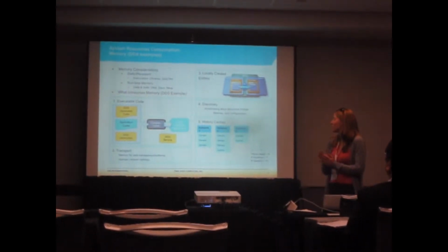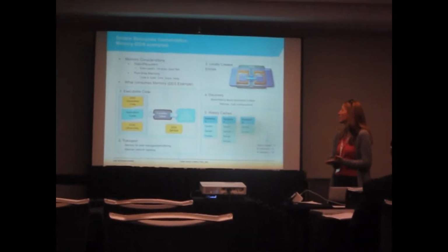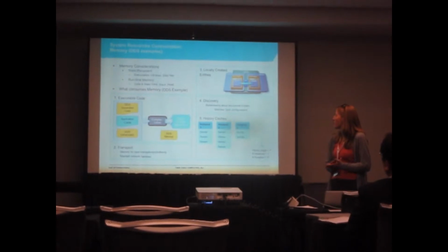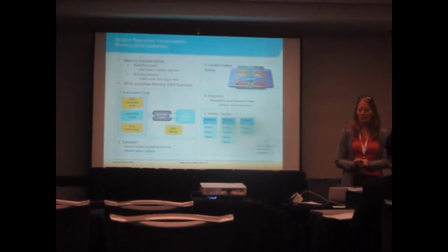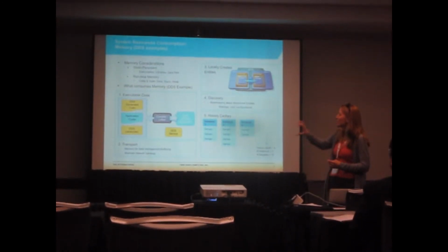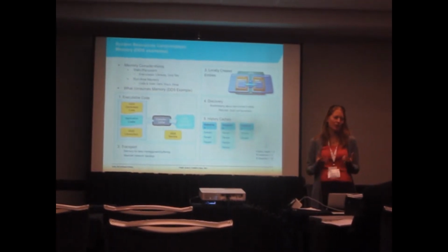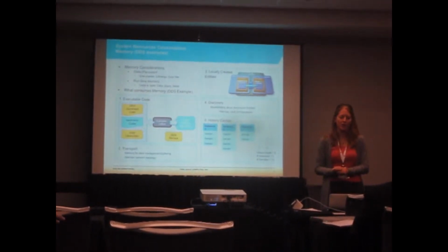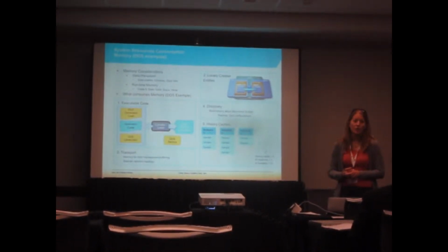All right, so let's get back to system resources and look at some examples here. So this slide looks a little bit at memory as one of the resources. And memory is used by a lot of different aspects here. We've got, of course, our static memory, right? We've got our application, we've got our library size, we've got all of those things that are going to take up memory. And then we have our runtime memory, we have our stack and our heap that we need to understand and make sure we manage.